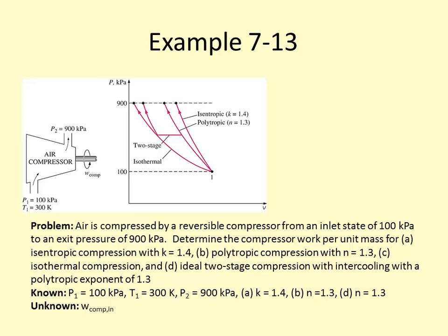And we want to do the one that has the best case scenario for us, which is when Px over P1 is equal to P2 over Px. So this is the best case scenario for this multi-stage cooling. So it just reduces down to this, 2 times all of this, and plugging in the numbers, remembering that Px is equal to 300 kilopascals.